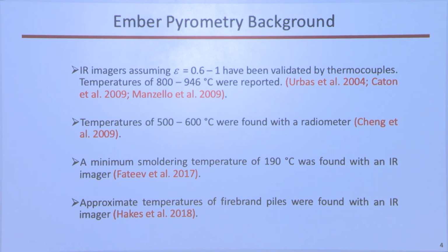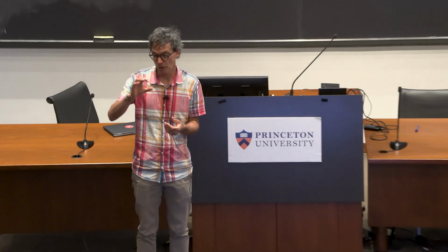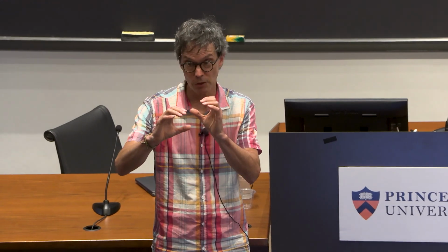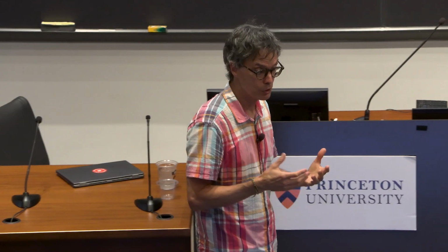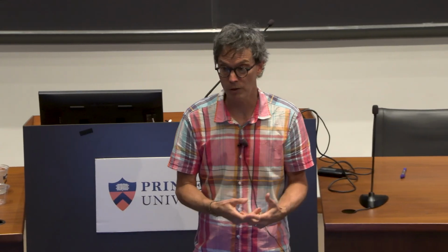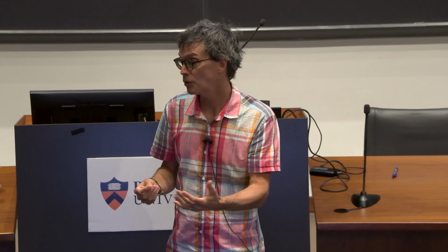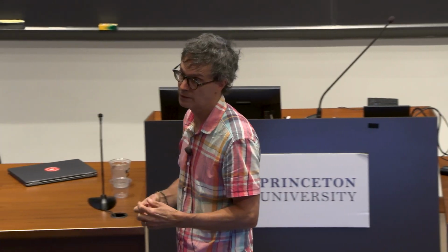And soot's a great place to do pyrometry because you can put a filter on your camera, take a picture, put a different filter on your camera, take a second picture, and from the ratios of these, determine the soot temperature. Not only that, you can also measure the soot volume fraction with this.